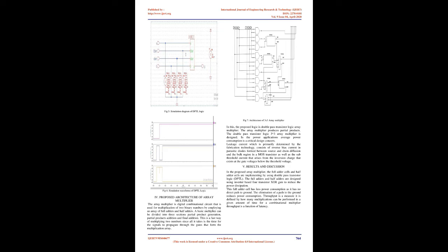3. Proposed circuit of EXOR gate. Double pass transistor logic, DPTL, is a modified version of complementary pass transistor logic, CPL, that meets the requirement of reduced supply voltage design. A PMOS transistor has been connected in parallel with NMOS to produce a full swing, like full supply or full ground, at the output to avoid the delay problems in the existing circuit.